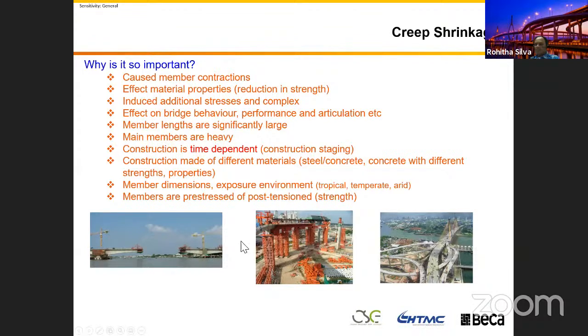You can see these bridges in these pictures, this balanced cantilever bridge, these post-tension bridges, that increases the significant stresses in there. In addition to that, the balanced cantilever bridge I mentioned to you before during my discussions, we calculate what we call the camber curve.